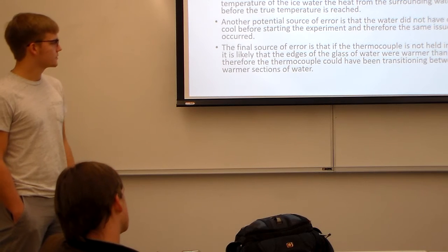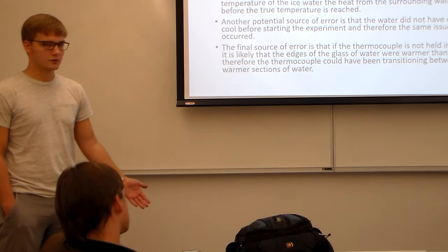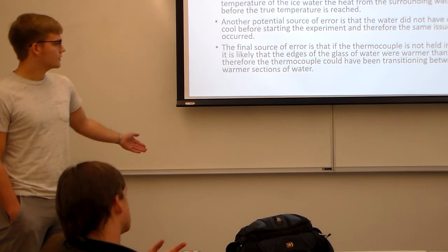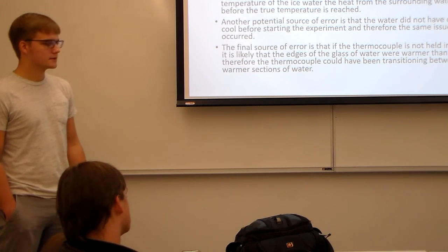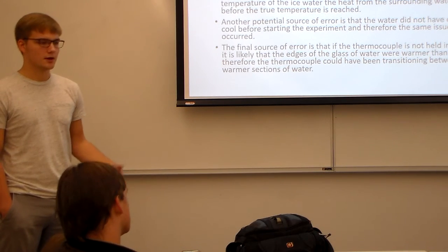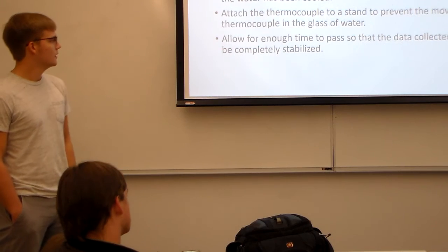Also, another potential source of error is that we possibly couldn't have cooled the cup of ice water enough. And then the final source of error that I found is that if the thermocouple is held in a static position, we're not going to get necessarily accurate readings.